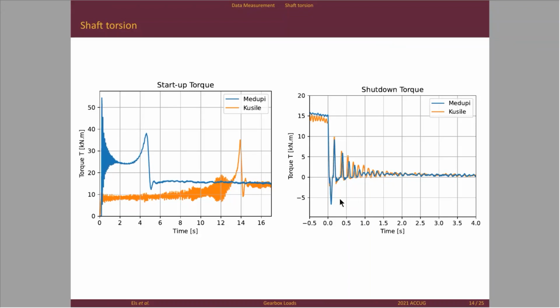They show at the backside of the gear, the non-working side, there are some marks. Now, I don't say it's that, but it's possible that here at shutdown, the backside of the gear gets a kind of negative load. So this is basically the torque that the gearbox experiences on the shutdown side.